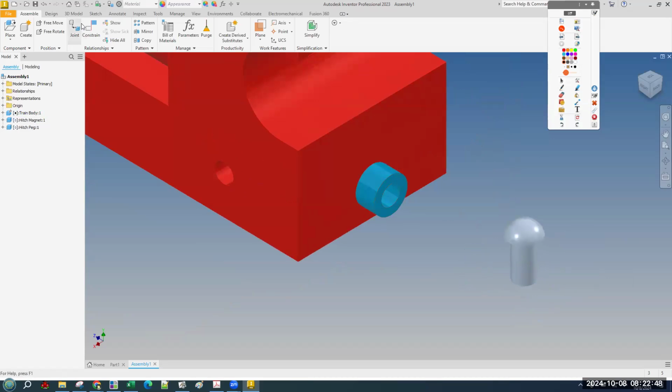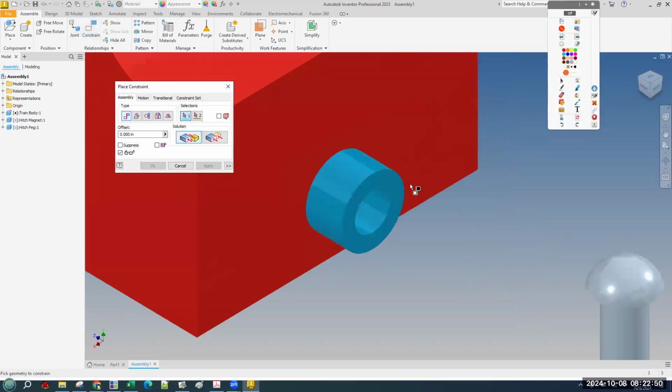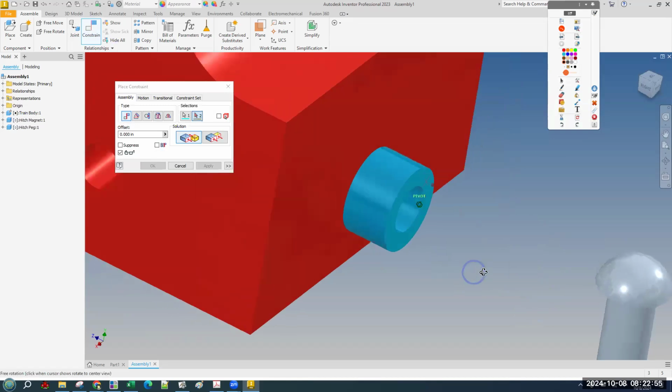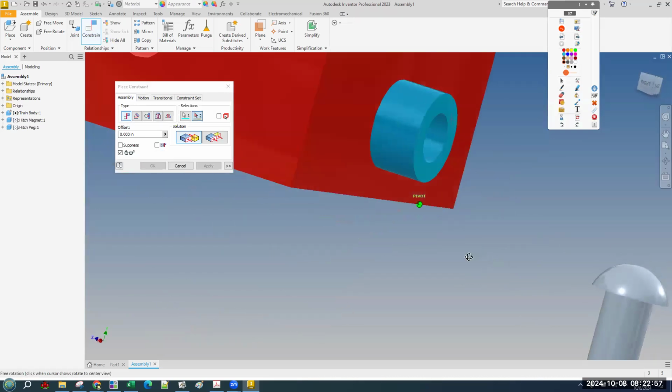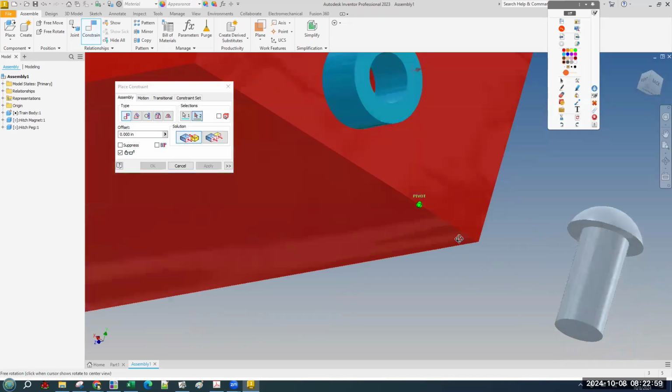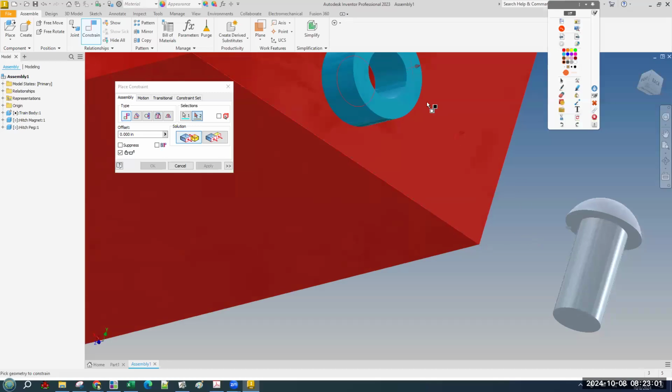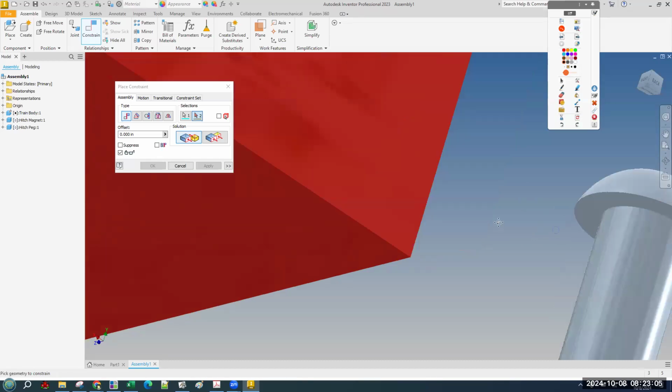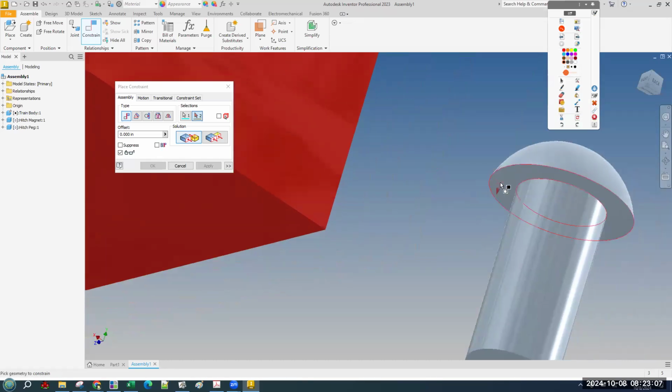We are going to constrain this face right here, sort of the flat part of the hitch magnet. Again, make sure you're not getting the green dot. And that's going to be what part of this is going to end up essentially glued to that. And it's this underface right here, underneath the head of the peg, there's this flat surface.